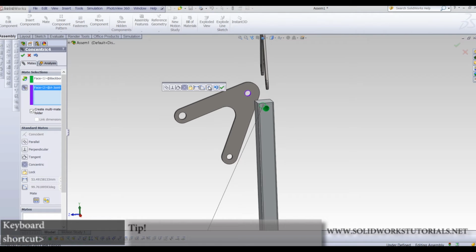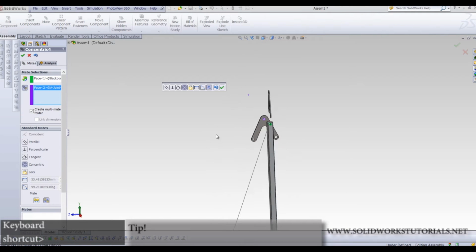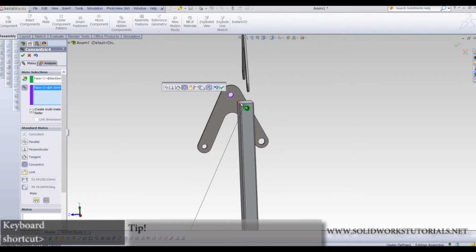What it does is it rotates it to the other way, right? But now I don't need it. You can either click it here or here. It does the same. You have alignment or anti-alignment. So let me just make sure. If I rotate it 90 degrees to the right along this axis here, which goes through this hole, the larger hole will be located on the bottom part. That's okay.